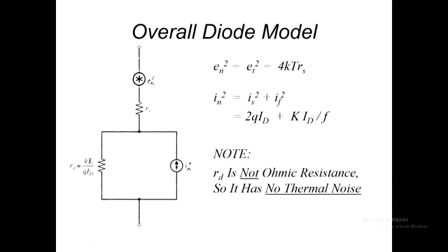The other resistor that we see here is an incremental resistor, modelling the relationship between current and voltage in the diode from an AC sense. And that's proportional to the DC current that flows. That's all very confusing, and we haven't really treated that as well as I would have liked, but suffice it to say it's a relationship for small signals, and it depends on the DC current that flows.